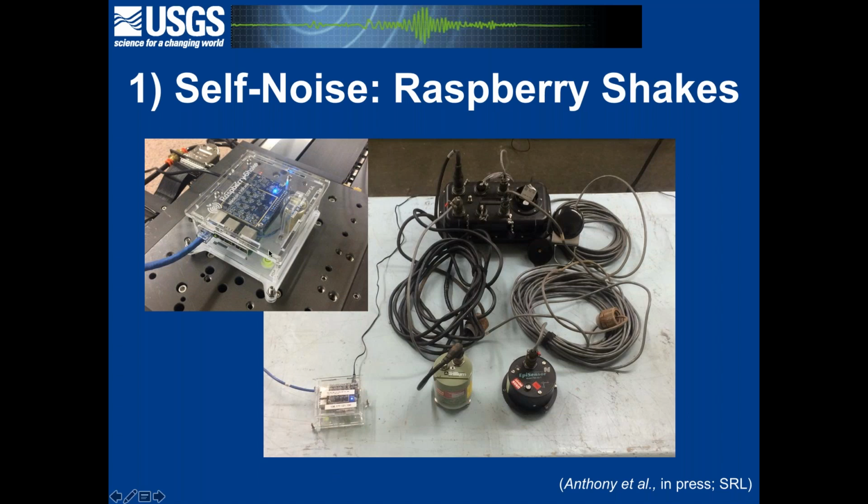So this has been proposed, since they're so low cost, for densification of seismic networks, as well as for earthquake early warning applications. And I'm testing this in relation to a USGS aftershock deployment, which consists of an RT130 digitizer, a Trillium Compact seismometer, and an EpiSensor accelerometer. So both of these things contain a weak motion sensor and a strong motion accelerometer and a 24-bit digitizer. The difference is that this is about 20 times more expensive than this, so keep that in mind.